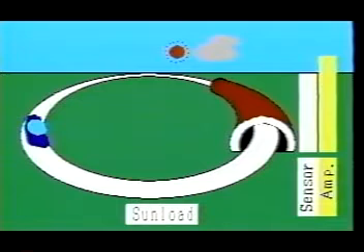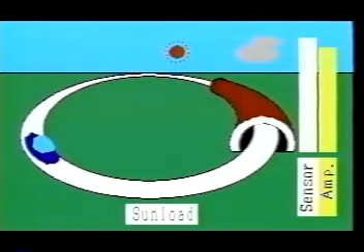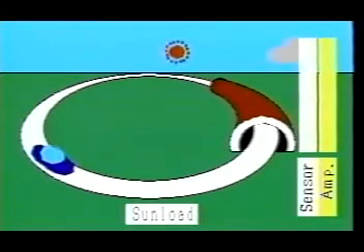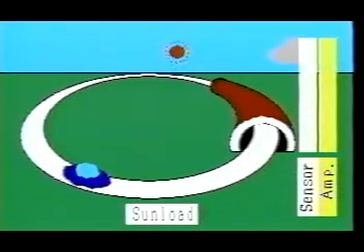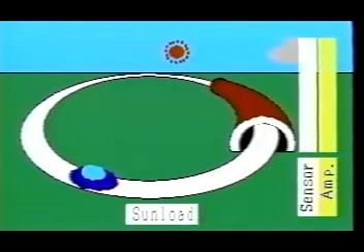In the case when the air outlet is set at the vent position, the low voltage of the blower motor will be changed by the automatic amplifier depending on the amount of sun load. If the amount of sun load increases, the automatic amplifier will increase the low voltage for the blower motor to maintain a comfortable feeling.